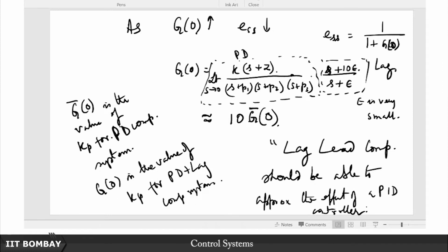This is good because, and indeed we have shown you piece by piece that this is possible, it means we do not need to resort to the use of op amps, and we will also be able to eliminate the noise that is always amplified because of the use of a PD controller or derivative action. So we can replace all of this with simply a lag-lead compensation.